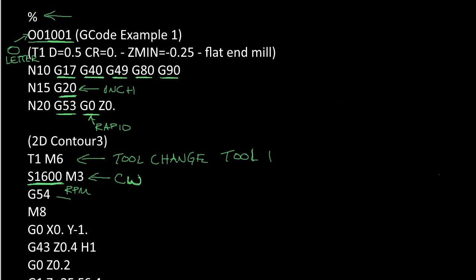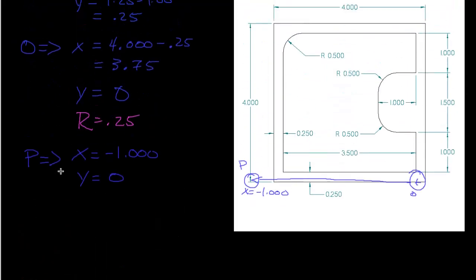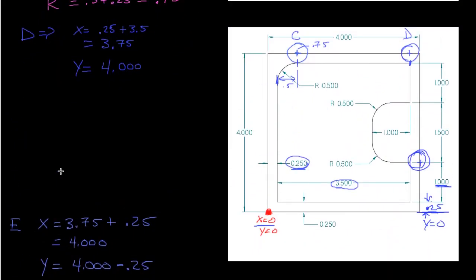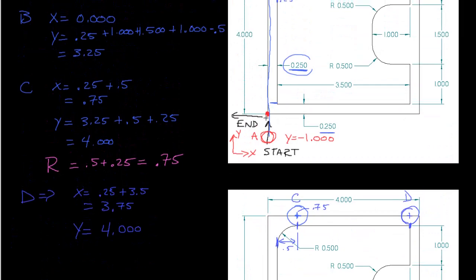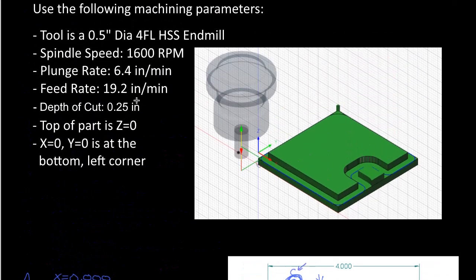Now I'm going to switch to my work offset mode. So all dimensions from here, all positioning from here is with respect to the G54 work offset. And this is something you'd have to do beforehand, and you basically program the machine to have a work offset at this corner right here, which we specified. We actually specified it in the program.